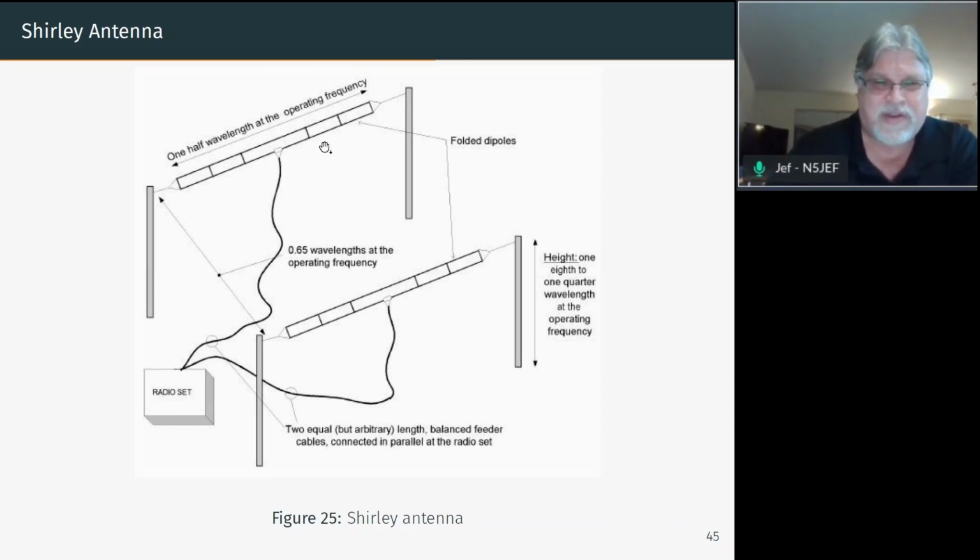They were using what they had in the field, and the impedance of the detonator cord was higher than normal, and so they used a folded dipole, which was about 300 ohms input impedance, rather than the 70 ohms of a regular dipole. And so really this complicated structure is all about matching the impedance of the cable that they used. As it is, just a regular dipole phased like this will give you the same performance, about double that of a single dipole, about 3 dB better.